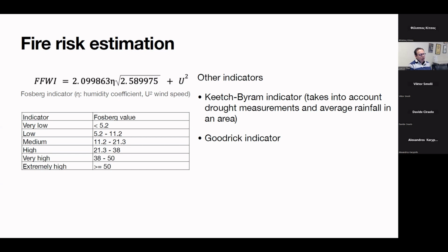But I have to clarify that the use of the sensor node is dual. One of its roles is to estimate the risk of forest fire, and the other role is to guide the civil protection forces in case of a fire incident. So this means that we have a different frequency of sending data. When we don't have a fire incident the frequency is lower, but when there is an identified fire incident, the frequency changes and we have more fresh data.